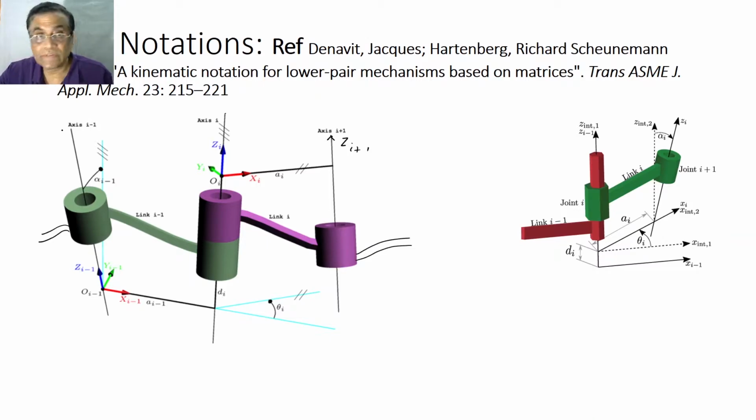Because with respect to the common normal, if this is the coordinate frame, the position vector of any point on the ith link will be completely unchanged, as long as it's a rigid body. Once we figure out the relation between coordinate frames, the multiplication will be with a known vector to get its position. Just earlier we discussed it also. I think it is clear, right? So this axis is actually describing the link length. About this axis the link length is measured.